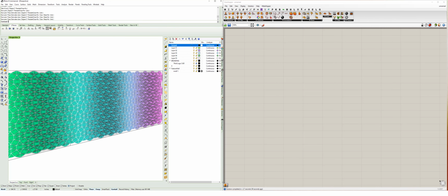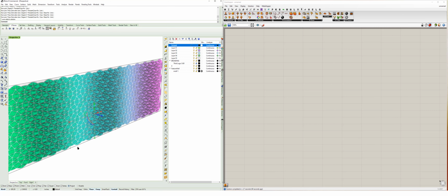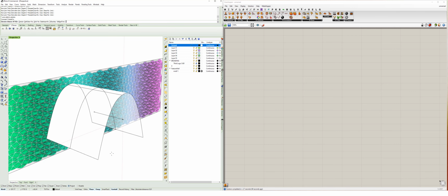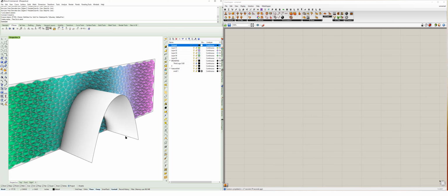Now, if you want to go ahead and split this geometry around that doorway, what you need to do is extrude curve. I'm going to go in both directions. I'm going to Control Shift select these two here, loft those into a surface.